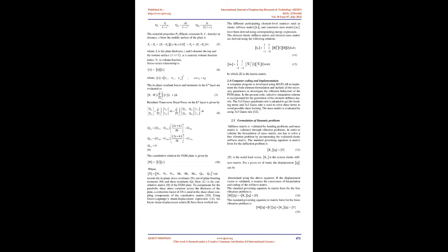Displacement variation is linear across the plate thickness, but there is no change in plate thickness during deformation. A further assumption is that the normal stress across the thickness is neglected. Properties are graded through the thickness direction, which follows a volume fraction power law distribution.